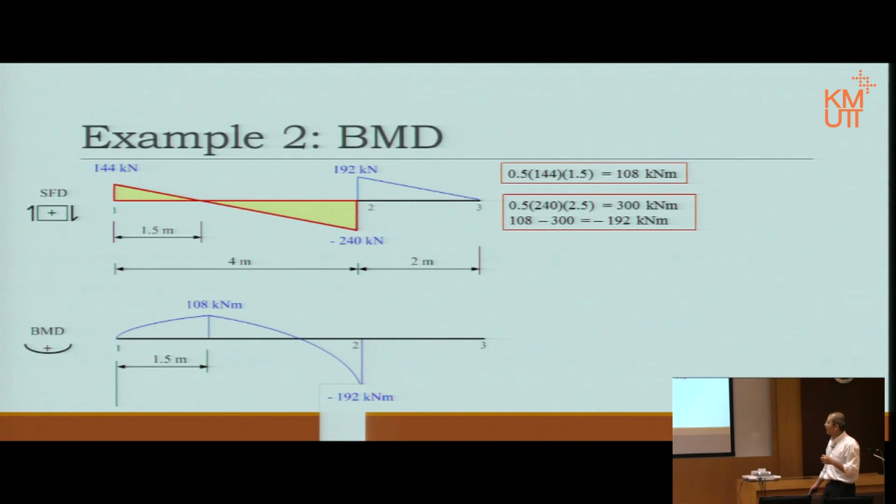Now we also have another cut 0 here. Okay, there we are. So we assume that it cuts 0 at the point of distance x. Okay, and of course the height of that shear force diagram at point x is equal to cx, because it's a straight line function. C is just any constant times x.